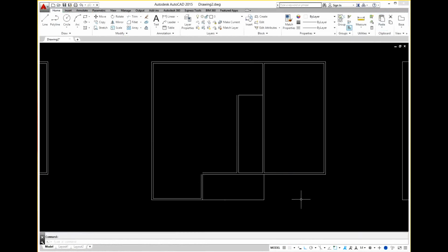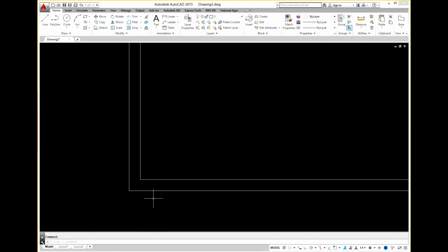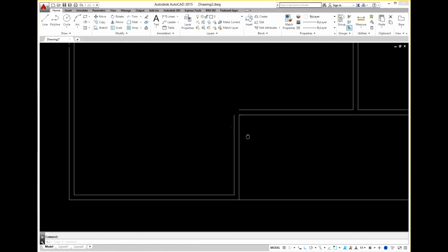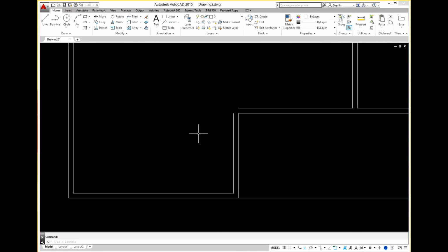This is where we left off last time. We opened up all the corners with the trim tool, but we have this intersection here, which is an outside corner, and for that we're going to use the fillet. So click on the fillet, it's on the modify palette, and then read the command line. It's asking you for undo, polyline, radius, trim, multiple.